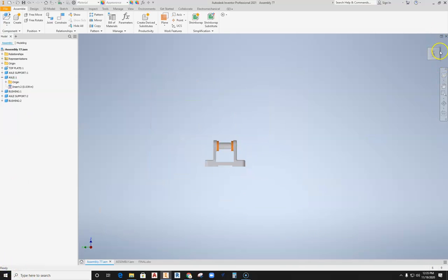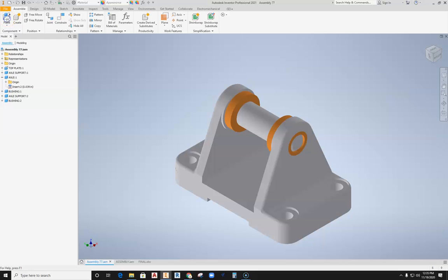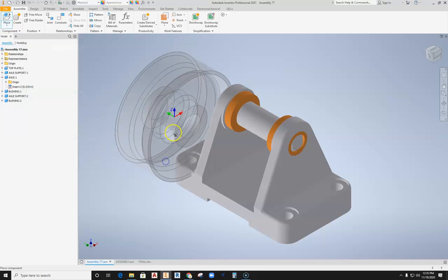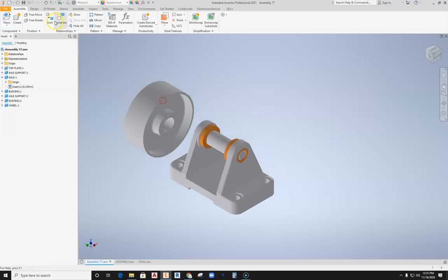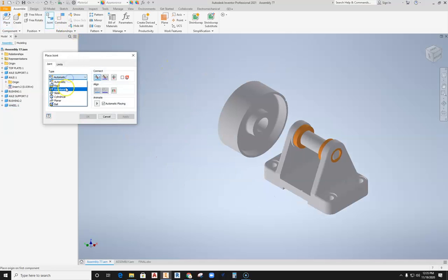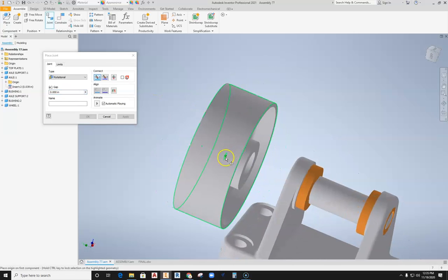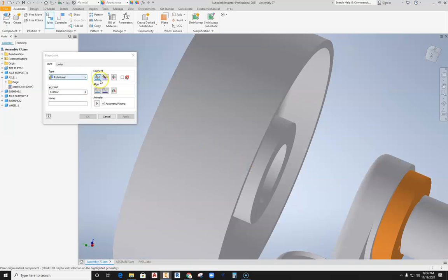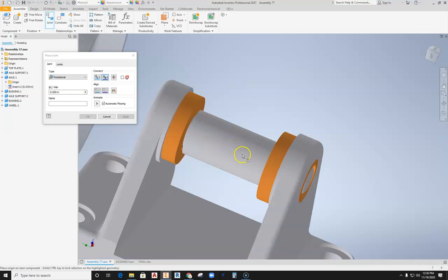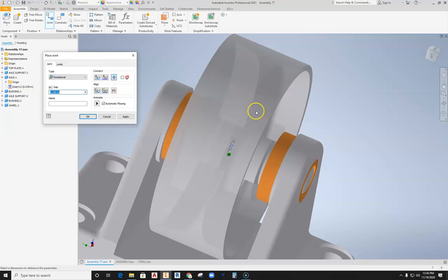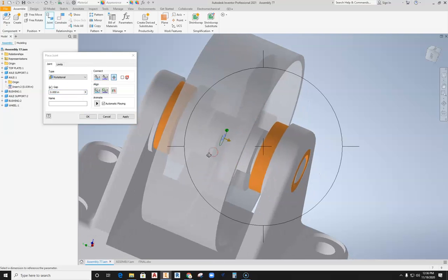All right, so the last thing that we need to put on here is the wheel. So I'm going to grab my wheel, which is here, drop this into my drawing. And then I want to use the joint constraint. And this time, I definitely still want a rotational constraint, but I want to mouse over this wheel a little bit because I want to find, that's it right there. I want this center rotational constraint, and I want that center glyph there to pop up. When that center glyph pops up, then I should be able to come over here and find center of the axle right here. That center glyph pops up. When I select those two, it should move the wheel so it's completely centered on that axle immediately.